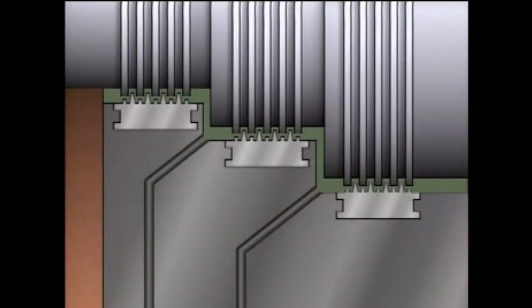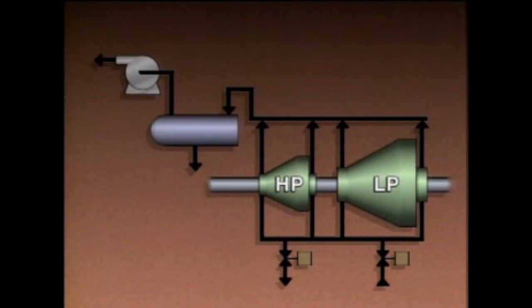The purpose of the exhaust system is to draw off steam leaking past the second seal before it escapes to the atmosphere. The system also pulls out any air that's leaking into the turbine. A typical Gland steam seal exhaust system consists of a Gland steam condenser, one or more blowers, which are called Gland steam exhausters, and connecting pipe.